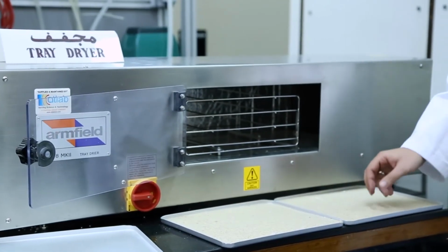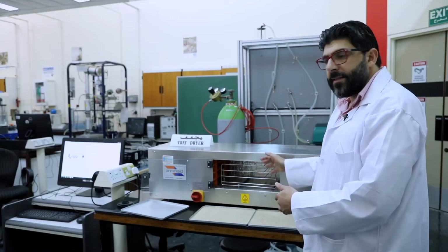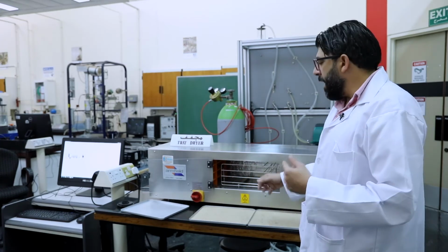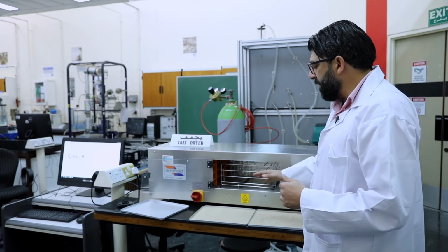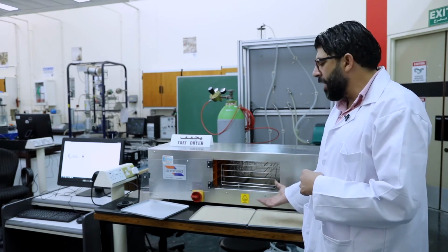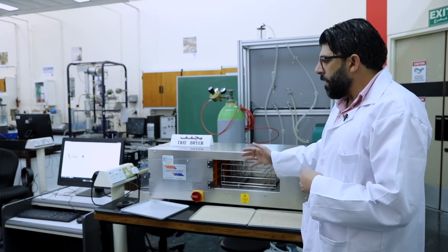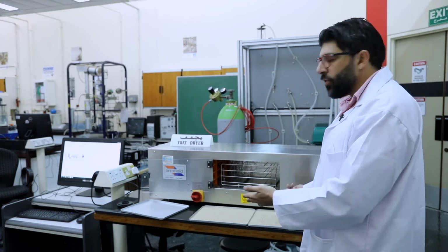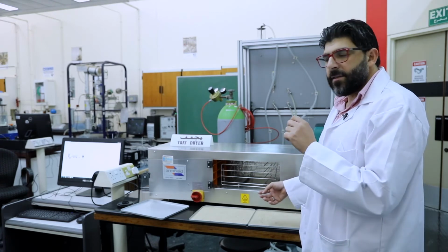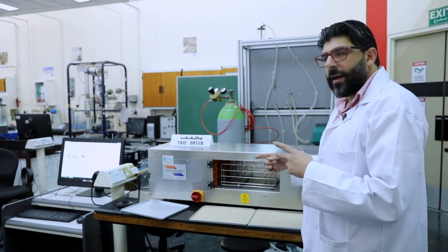Okay, so first we should calibrate the balance and make it 0 on the software, and then weigh the empty trays. Then we have 2 options: either determine the dry weight of the sand and then put water and measure again, but we don't prefer it because sometimes the sensitivity of the balance changes over time by the effect of heat, so you can get some error.